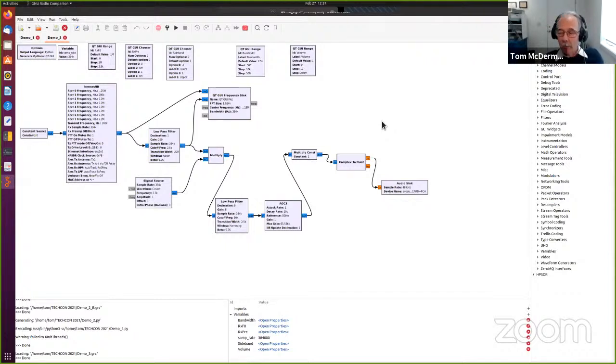And so if you have a Red Pitaya and you load his code into the Red Pitaya, it will talk OpenHPSDR on the output, and then you can use this module to stream samples into your flow graph. I wrote this Hermes module about 8 years ago, and have been updating it, and it's been used in a lot of science and a lot of ham experiments. So we'll look at the output of that on a spectrum analyzer.